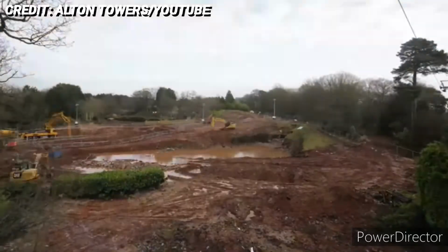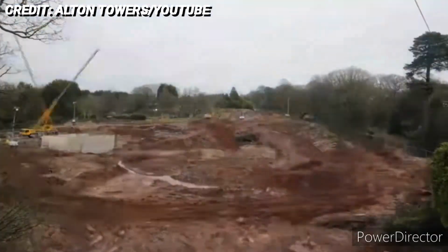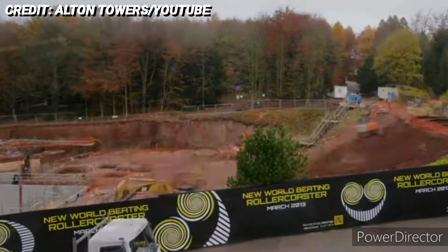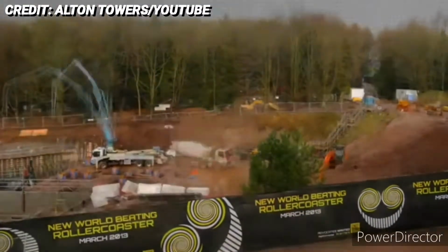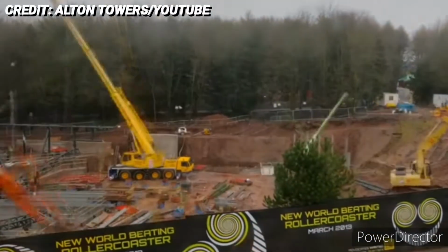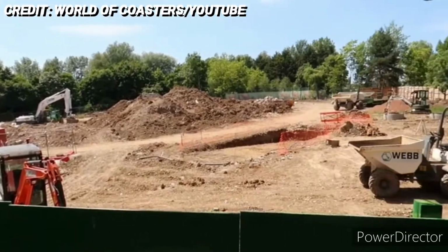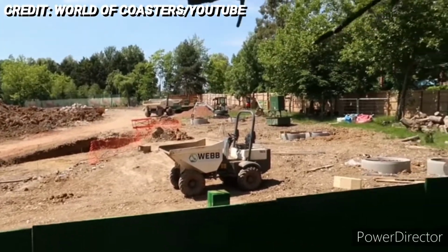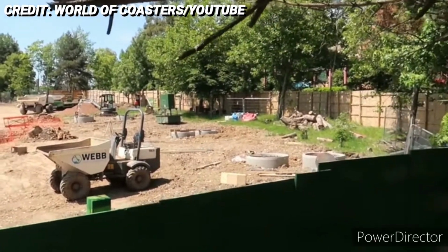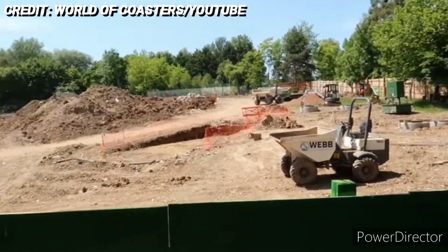Once the full ride plans have been approved, groundwork for the roller coaster can begin. First of all, the site where the ride is being built must be completely cleared of all existing structures and objects in order to make room for this attraction. Then, once the site has been fully cleared, concrete must be poured into the ground to form footers in a specific layout that shows exactly where the support columns for the roller coaster must be installed.